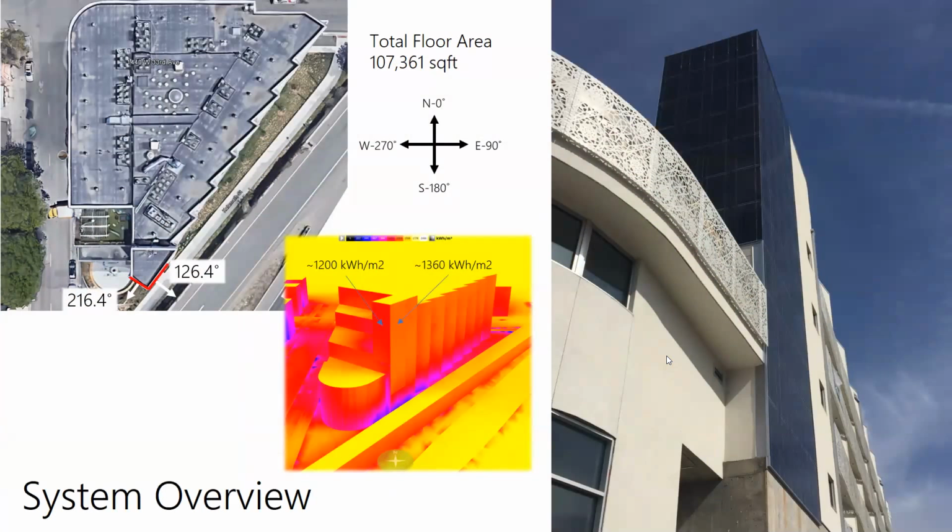So the broken up nature of the rooftop array required the architects to think outside of the box. They thought about laying out PV on the roof, but it was just far more elegant to put the PV on the facade. The system consists of 28 panels facing southwest and 55 facing southeast, amounting to 20.75 kilowatts.